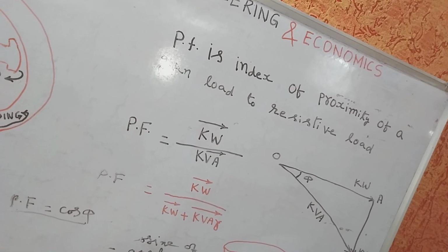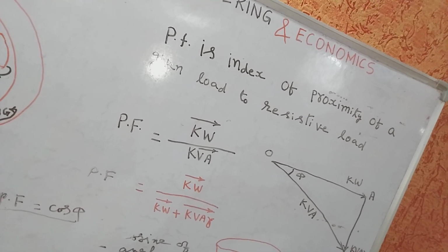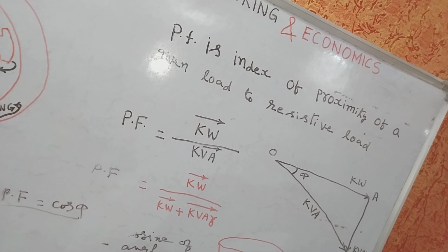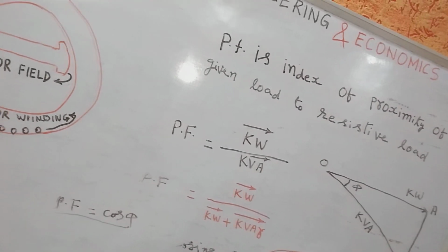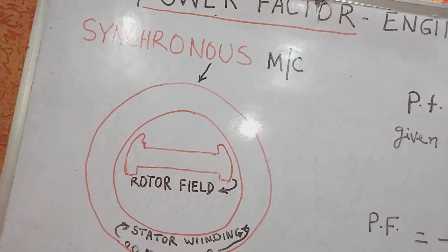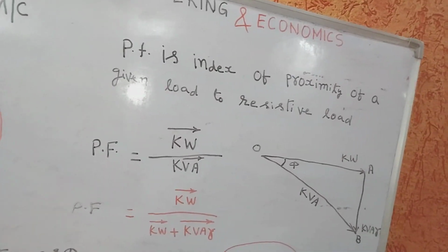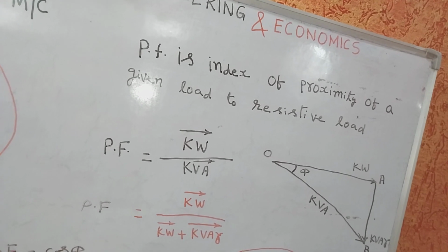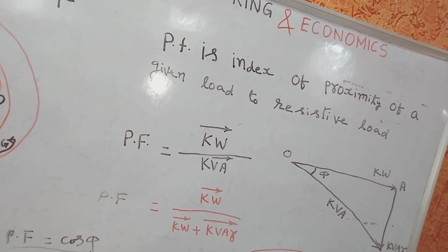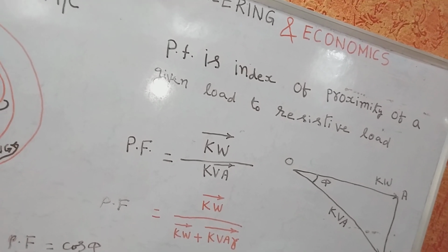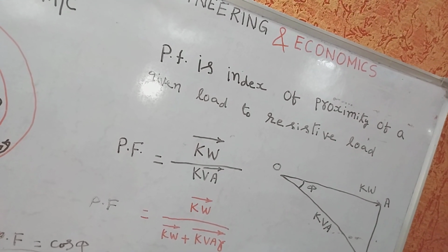It makes no difference in the magnetic circuit or in the fundamental energy conversion process whether this magnetizing current is carried by the rotor of a synchronous machine or the stator of an induction machine. Just as it makes no basic difference in a transformer which winding carries the exciting current.